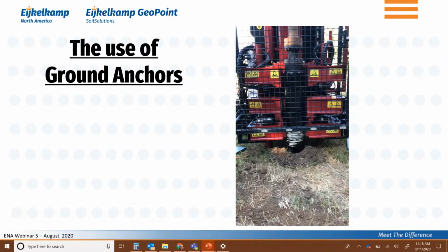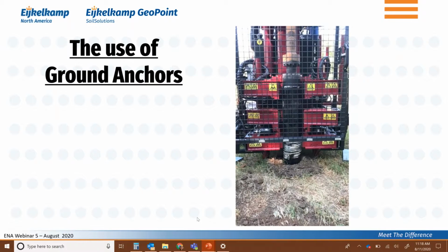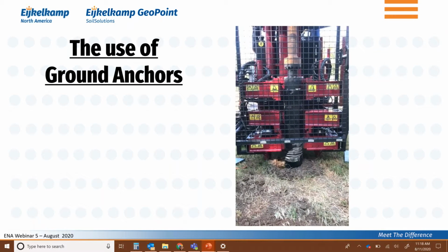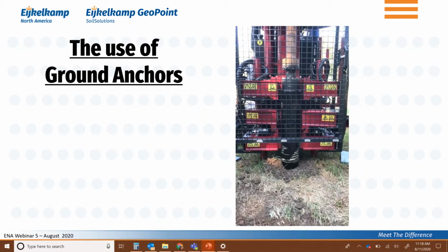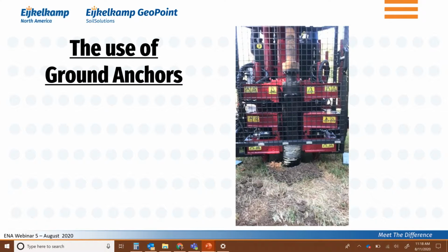And what you then can do after that, if I go to the next video, is just start to rotate this auger into the ground. I won't show you getting this whole thing in the ground all the way, but you can go to whatever depth is required to provide the additional reaction force that you can then use together with the weight of the drill rig, so that you have the 20-ton capacity available.